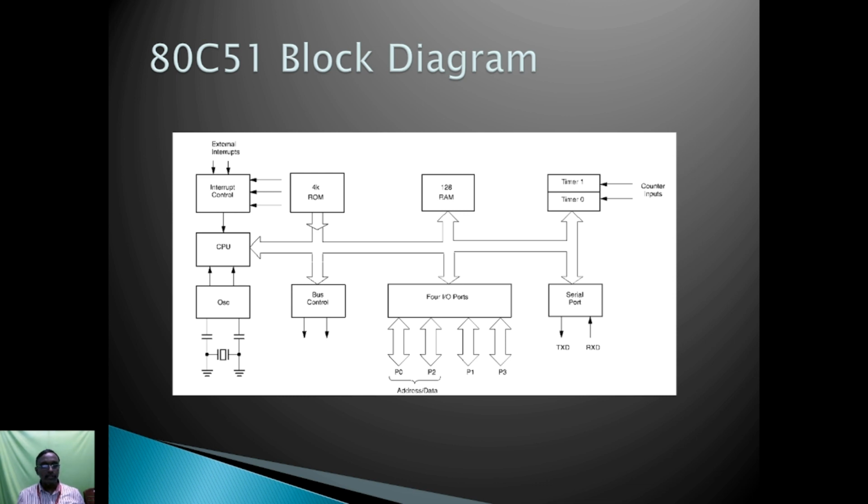The oscillator means that a crystal oscillator is employed in the 8051 microcontroller. The crystal oscillator has 2 capacitors and is connected with a crystal of oscillation. It determines the corresponding frequency of the microcontroller. So we can determine the frequency of the microcontroller with the oscillator only.